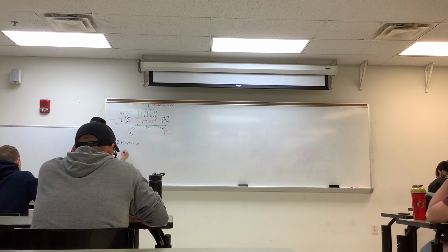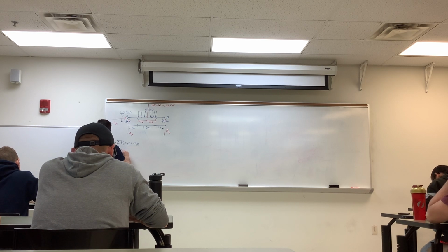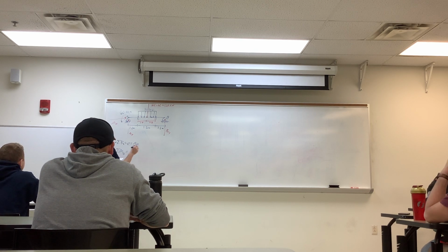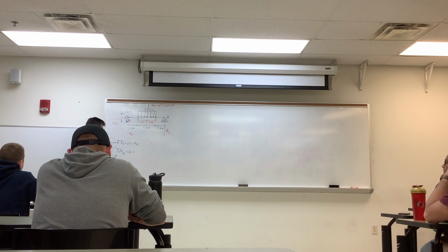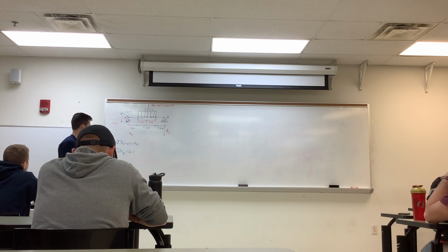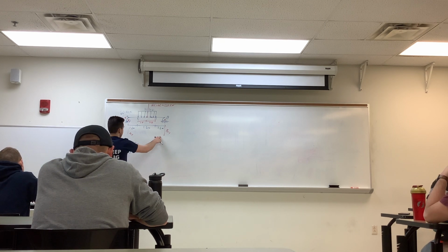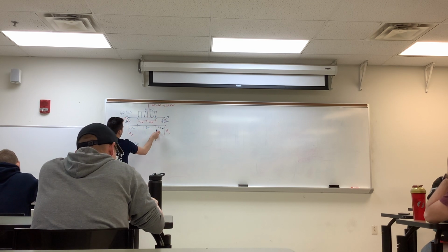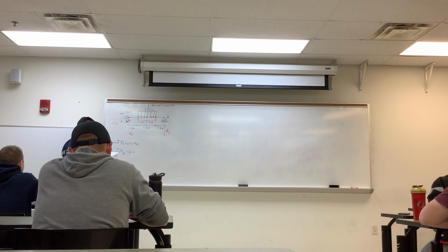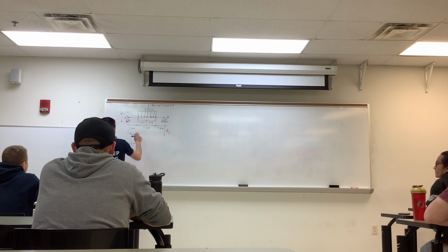Next, I'm just going to sum the moments about B here. You could do it for A, it would also work out. Sum the moments, with counterclockwise as positive, all equal to 0. The reason I made it counterclockwise is just to have this 60 kilonewton meter moment as positive, for simplicity. The things that cause a moment about point B are this 128 kilonewton force at an arm of 2 meters from point B, this 60 kilonewton meter moment, and then AY.